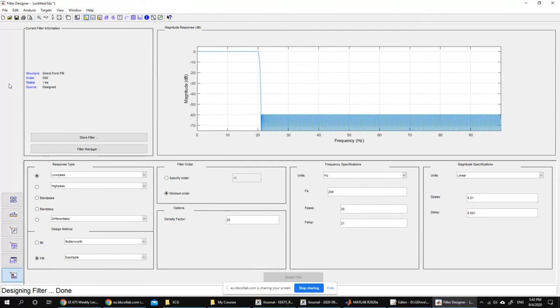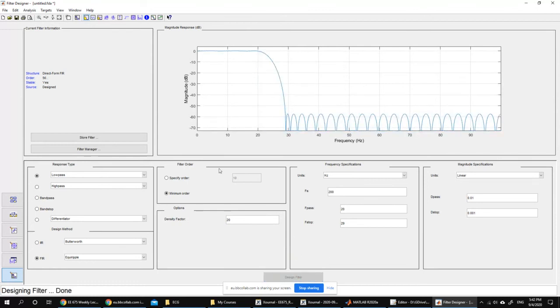How about if we remember that we would like to remove a 30 Hertz signal? We don't have to start the stop band from here. We can stop it at 29. Let's try to have this as 29. The order now is half what we started with. Instead of having 102, we have now 56. And still, if you see here, the 30 Hertz will still be attenuated by -60 decibels, which is 1/1000. So this looks like a much more efficient way of doing this.